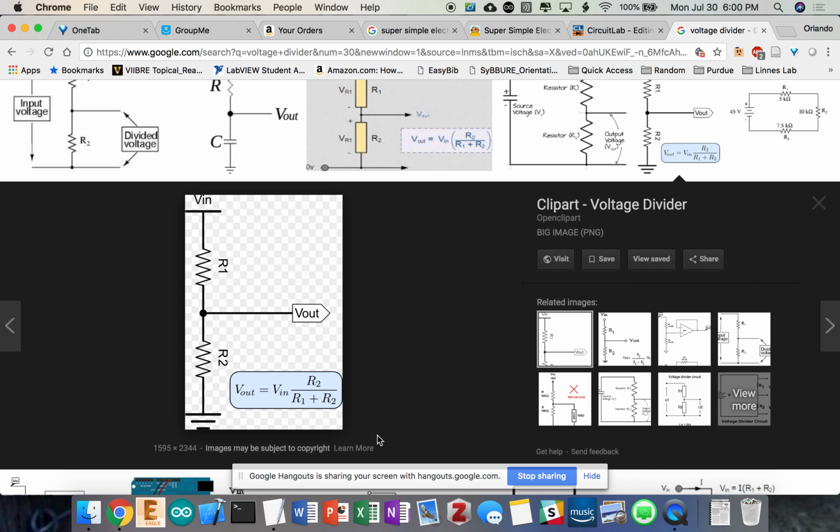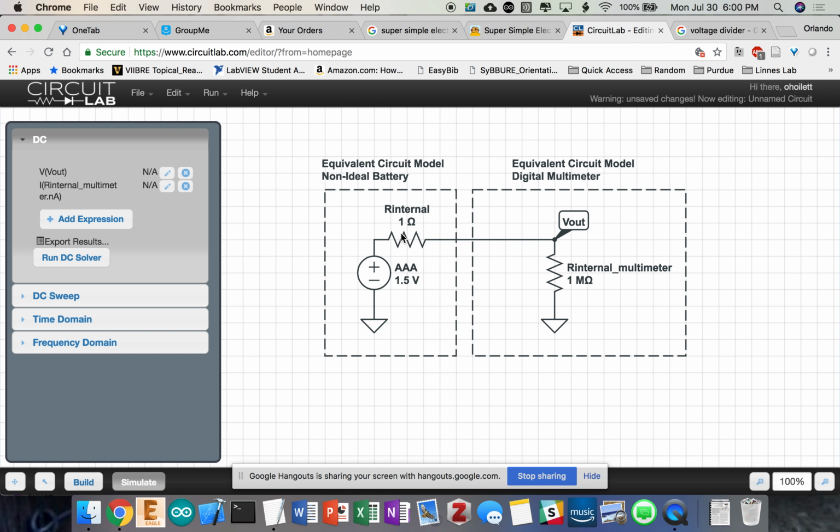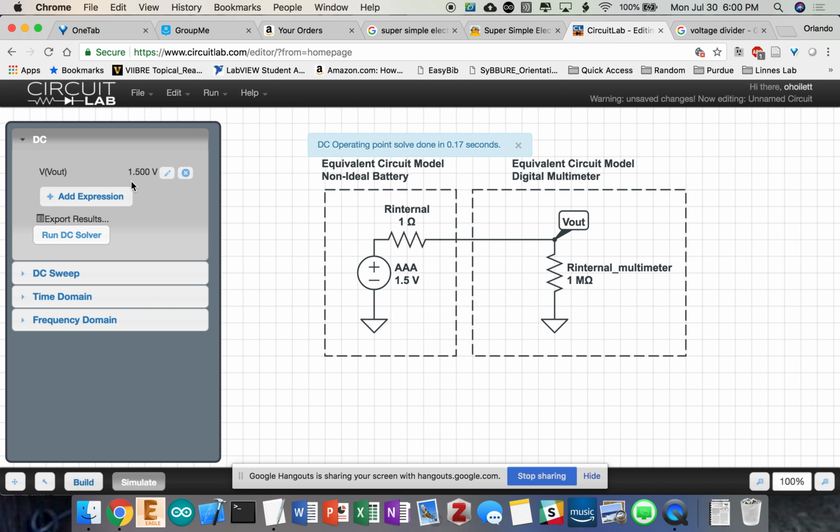Basically, you're not getting any resistance then on the voltage. Yeah. So what's V out? Basically, the V in, right? Yep. Perfect. Okay. So if R2, in this case the internal resistance of the multimeter, is much, much bigger than R1, V out is essentially equal to V in.